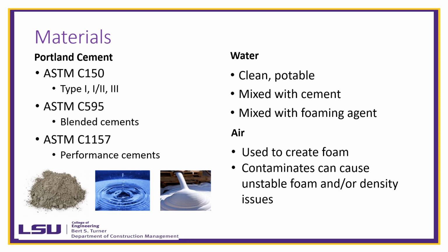You mix it with the cement and you mix it with the foaming agent, so you want to make sure there's no contamination in your water. And then we have the air, which is used to create the foam. Contaminants in your air or in your air compressor, like oils, can cause unstable foam and/or density issues.